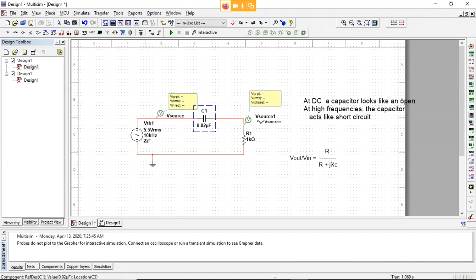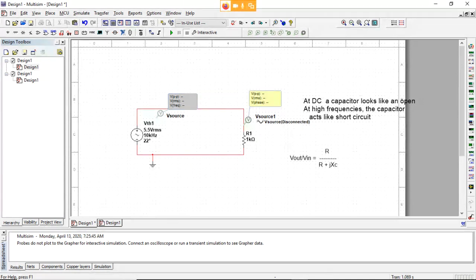Remember, I just said it over here. This is like a short circuit here. Okay, so this is your circuit here. There's no capacitor, and so you're taking whatever's coming in and just passing it right through into your next circuit for the most part. Whatever this voltage in is, that's what your voltage out is. It's a gain of 1.